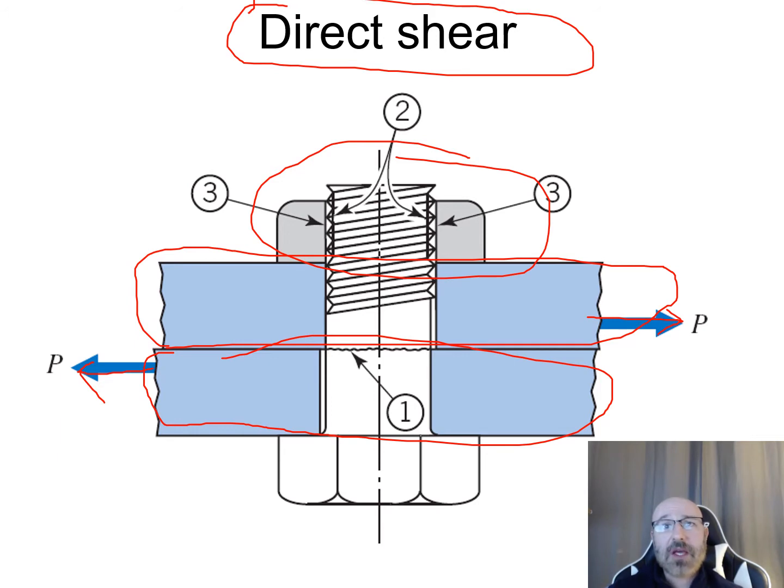Now the question may be a couple things. We could ask, what is the shear we're going to see on this bolt if we already know the material? Or we know that these loads are going to be something, and we can back out the shear that we're going to experience on this bolt, what material it should be, what diameter it should be. Whether we're given the bolt material, the bolt diameter, or this external load, those are all things we could solve for. It might be a problem where they tell us all the material types, diameters, and dimensions, and ask what is the max load we can see before we damage the bolt, or whatever may happen. Those are all different types of things we could do within a problem like this. But this is just one application where we have direct shear occurring.